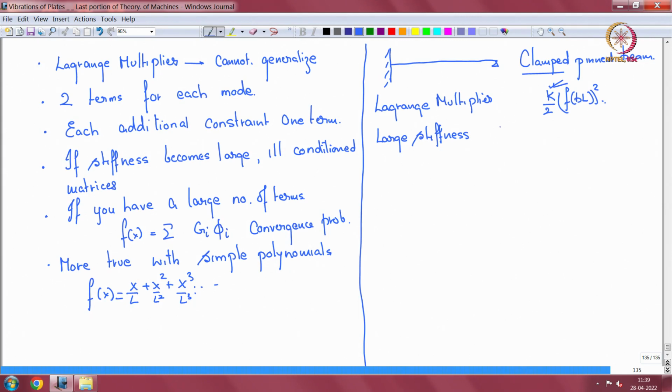Then it becomes a pin joint or support or restraint, a pin support. However, as I have been saying in this section, if k is sent to a very large value, then numerics can become a problem, because some elements in the matrices will have very high values.